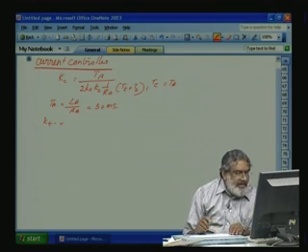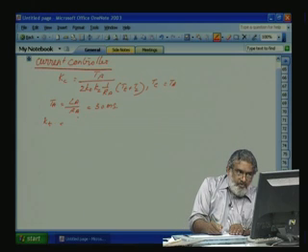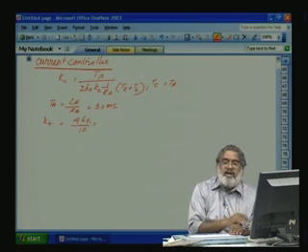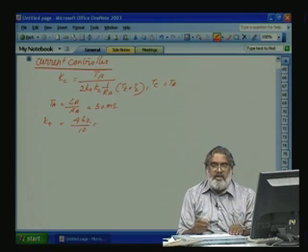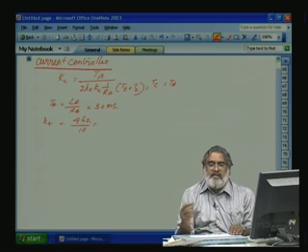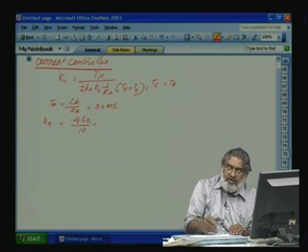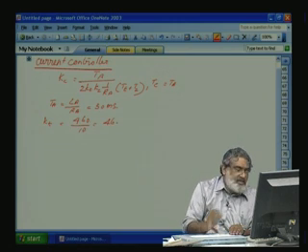So, the gain Kt is equal to 460 divided by 10. That means the moment 10 volts comes, the firing angle should go to such a level that the 3-phase fully controlled converter output gives 460 volts. So, Kt is equal to 46.